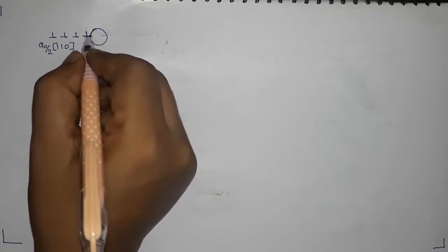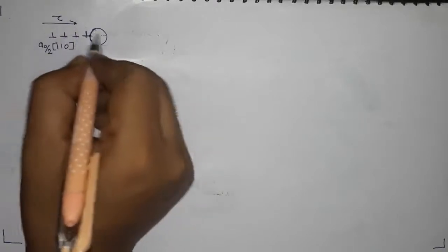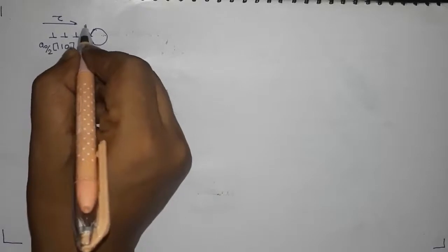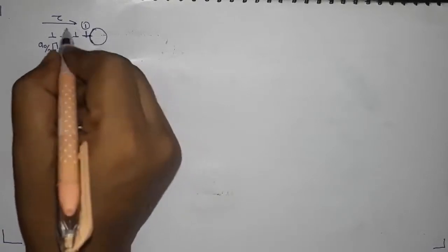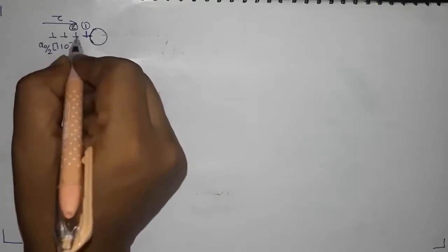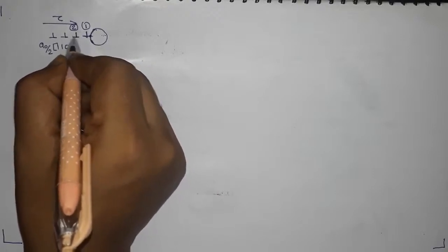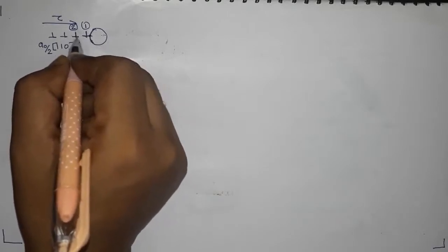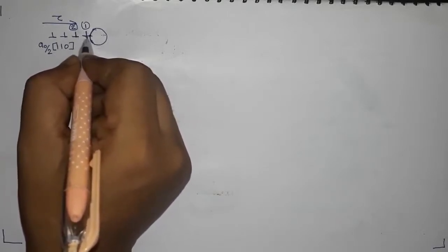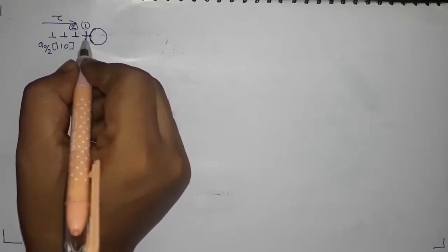Okay, so this dislocation now cannot move, and I am applying a shear stress and asking them to move. So dislocation number 1 moved, reached this boundary, now it cannot move, so it stayed there. Dislocation number 2 moved and it cannot go any further because there is a repulsion between dislocations of the same sign, and you see these two dislocations are exactly the same, so two half planes cannot be together because that will create more strain in the lattice.